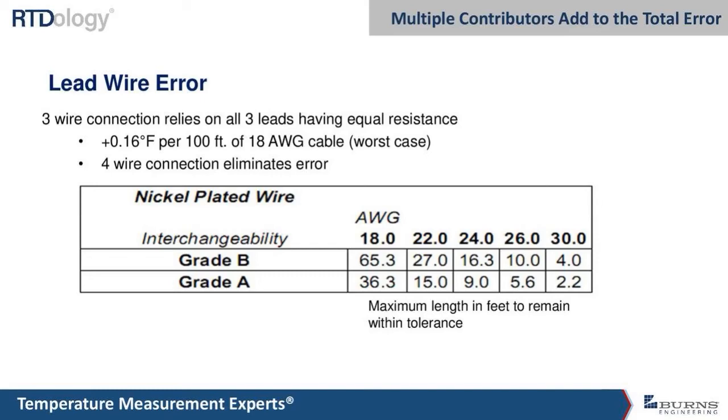So they were seeing some stem conduction initially. What we ended up doing there was taking a longer probe, since they didn't want to extend down any more than about 4 inches from the ceiling to maintain headroom. They ended up putting a 90-degree bend in a probe that was probably 15 inches long. We just went down, made a 90-degree bend in it, and that eliminated the stem conduction error. I don't know if 15 inches was the magic number. It may have worked well with 10 or 11 inches.